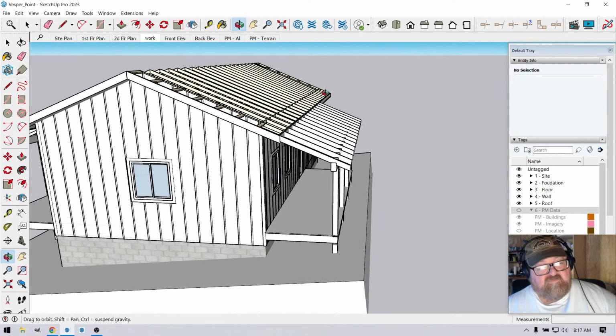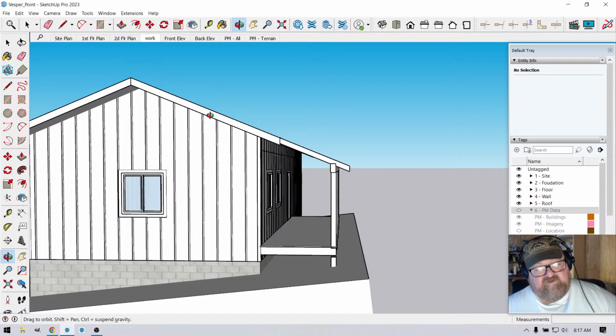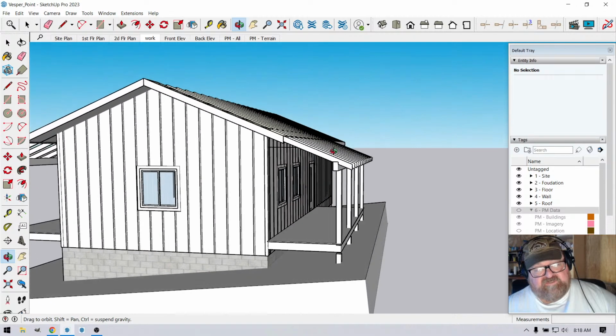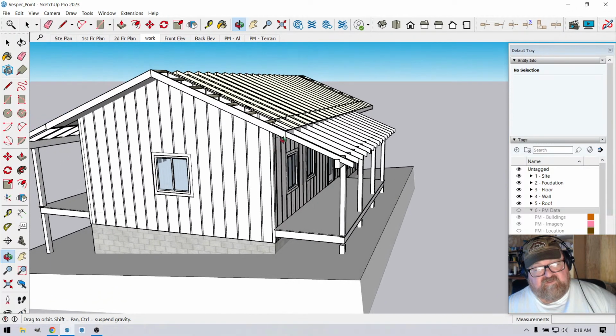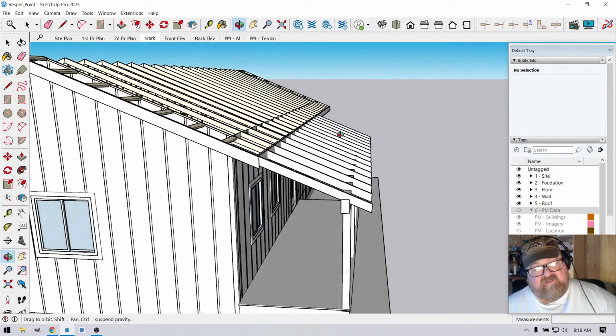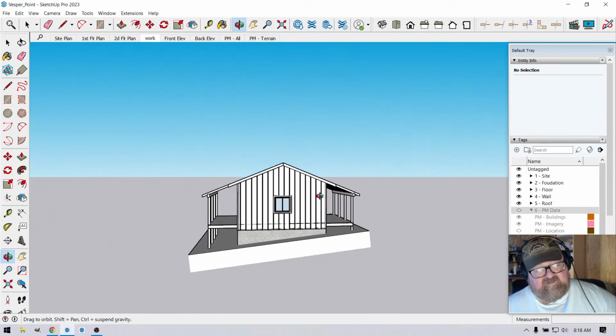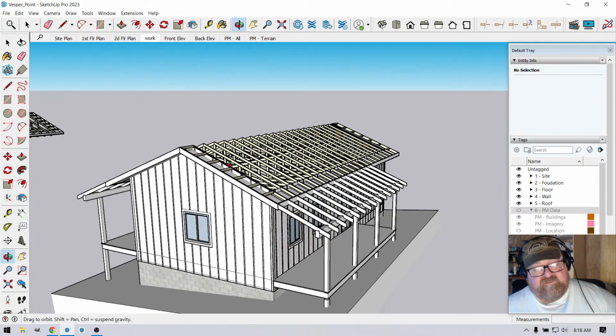So if the main part of the roof is low, and you can't, and it's down here, well then you want a steeper pitch roof, so it'll come down and it'll break right there, because your porch beam is fixed. You can't just keep lowering the porch beam to get what you want. So what he wanted was, I keep hearing my phone vibrate. What he wanted was just a straight roof line, which I think looks better anyway. Looks cooler, and it's easier to build.